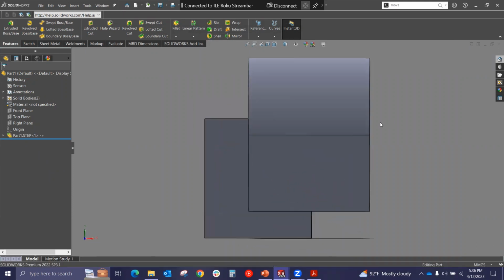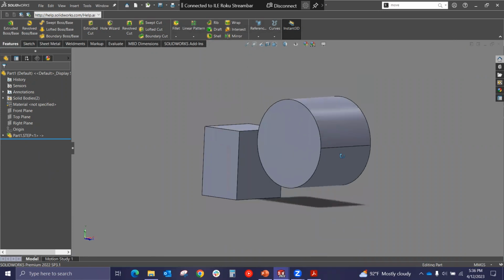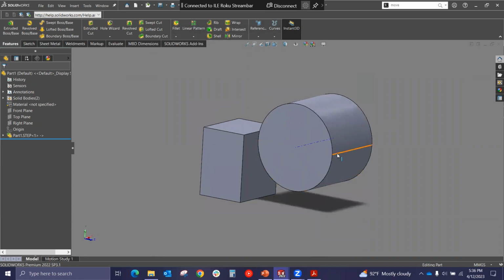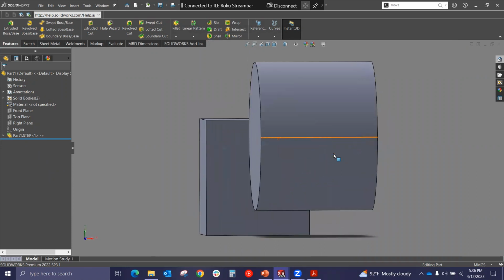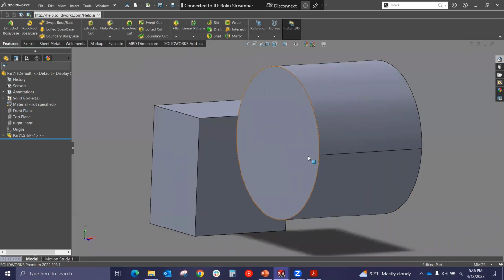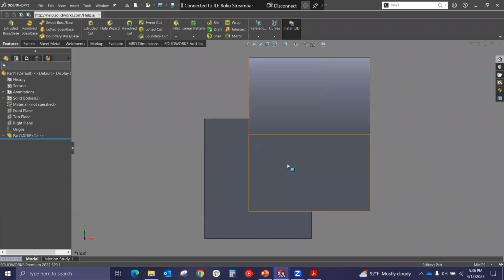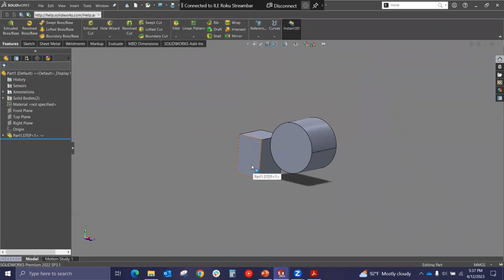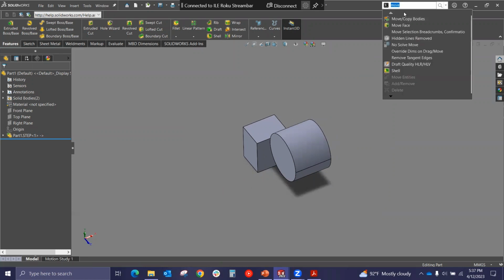I'm not sure what improvement was made to the coordinate system, but there might be something in the coordinate system where you can add your own coordinates, maybe export using that, but I'm not sure. And he's right, when I reverted, this is my front view on my imported geometry. But you could use the copy bodies to get it onto the oriented one, right? You could technically re-export it, re-import, get rid of that, put the copy bodies, have that like this. Yeah, true, good point.